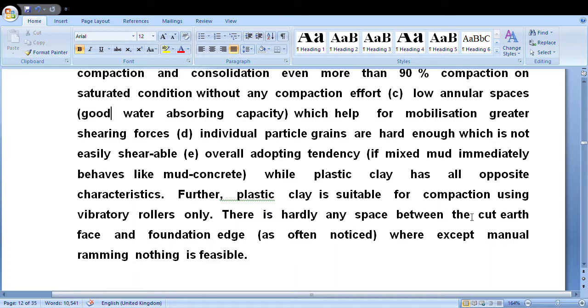But small vibratory rollers are available nowadays, up to 300 size. If we use that type of roller, we can compact the backfill material up to the required amount, and assure that our structure is totally safe against settlement failure.